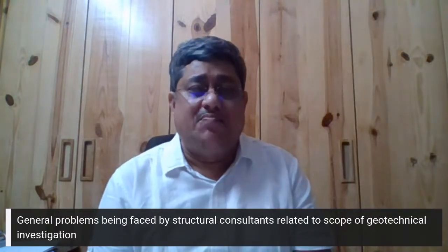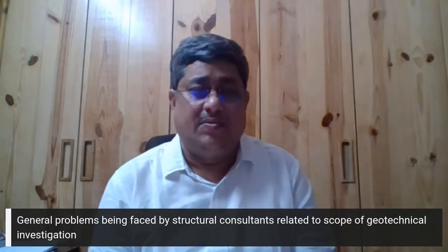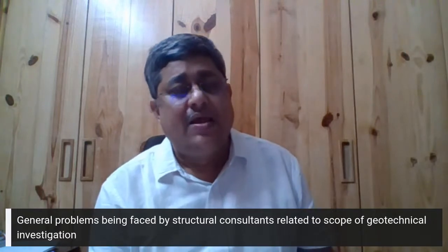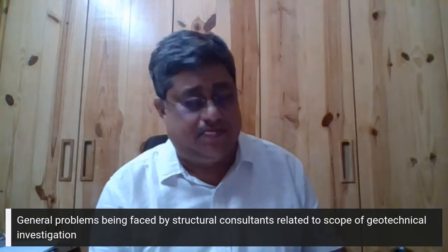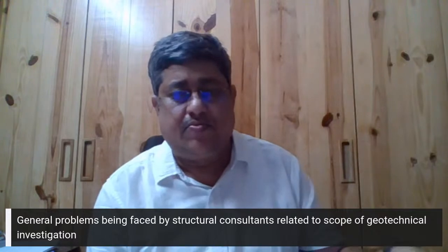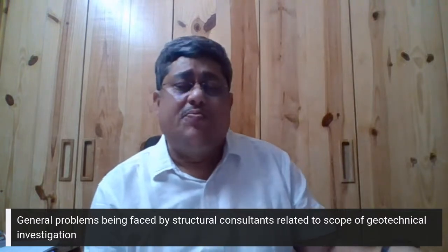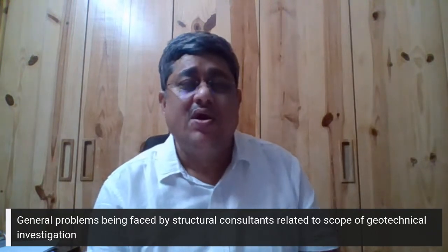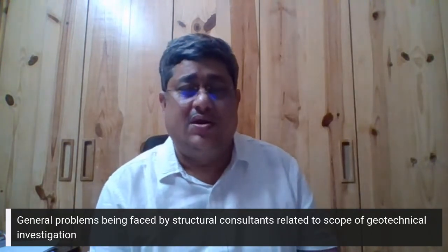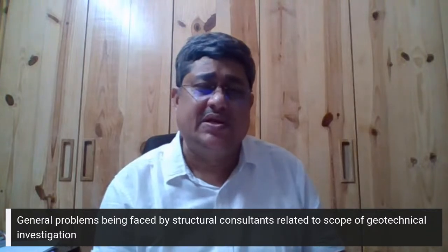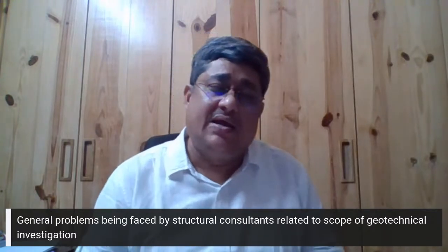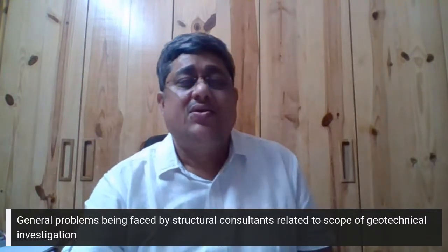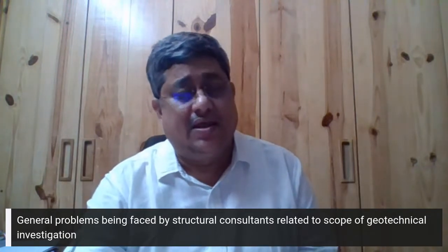I will give you one example from my experience. In one area I found that a proper soil investigation had not been carried out. The results were not justifiable, they were absurd. So I gave another company the job of investigating the same area.